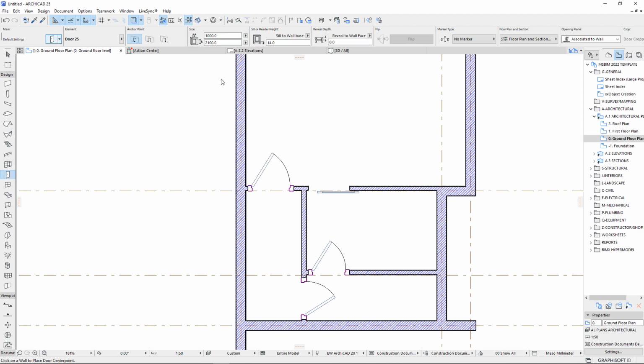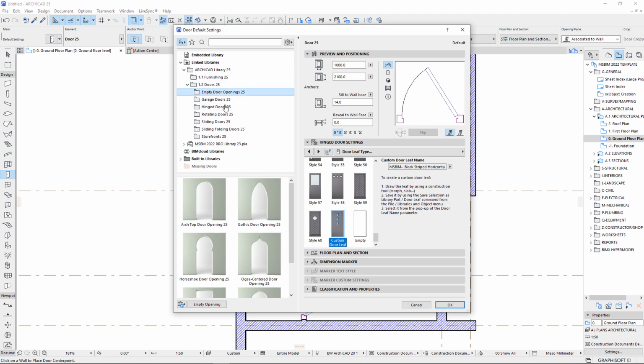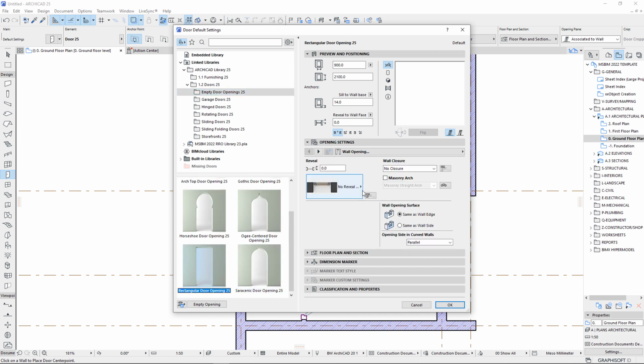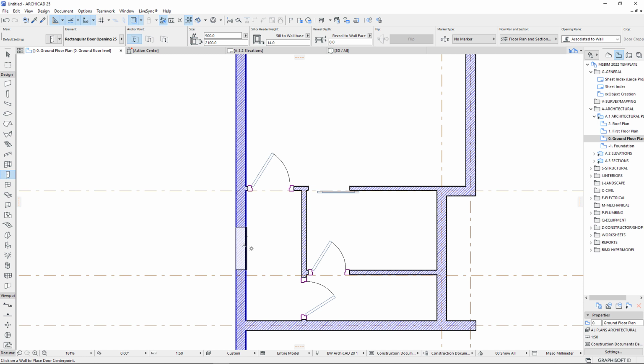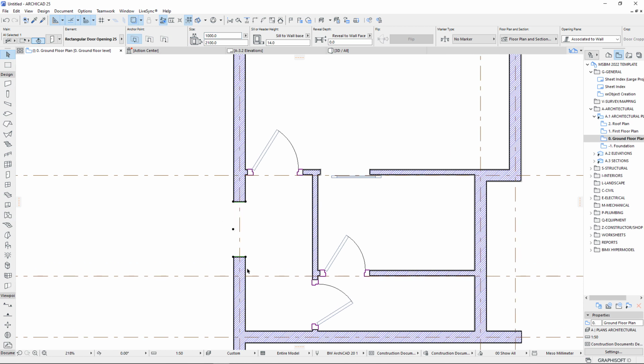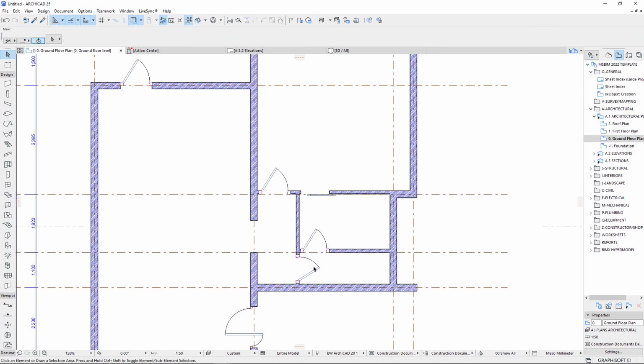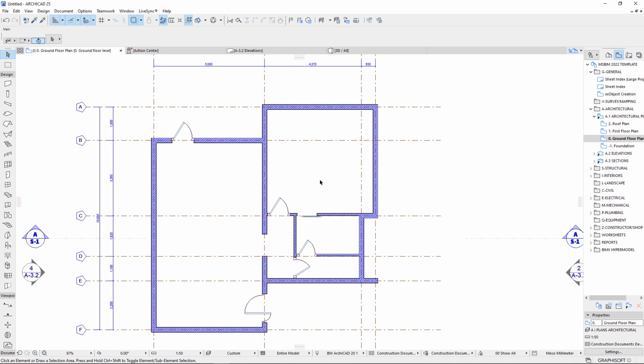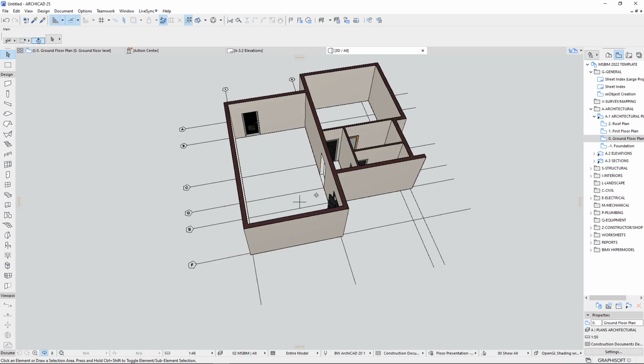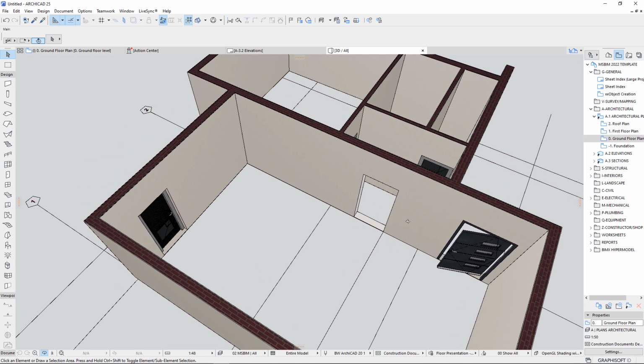opening. So go to the settings, and under empty doors, let's just click on that, and there's nothing that you really need to set for this because it's just an empty, except the width. I think let's make the width 1 meter. There we go. Then I'll make sure it's right on this line, on the grid line. Perfect. I think everything is super now. We can check this in 3D to appreciate the results.